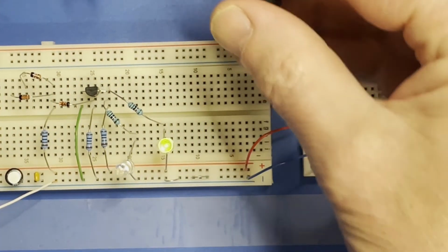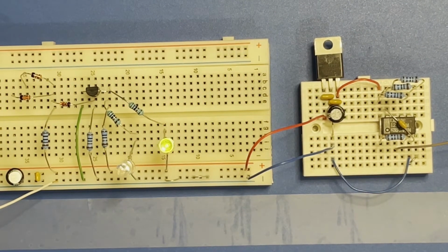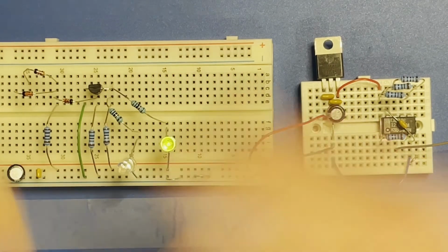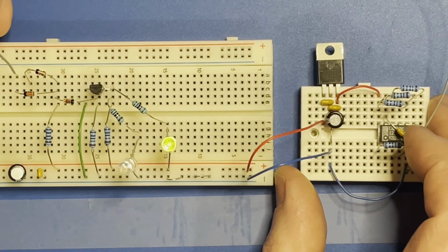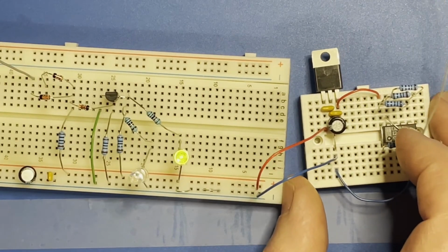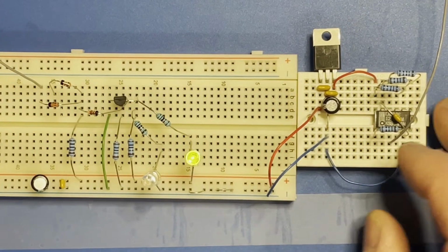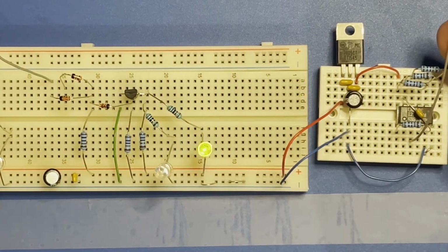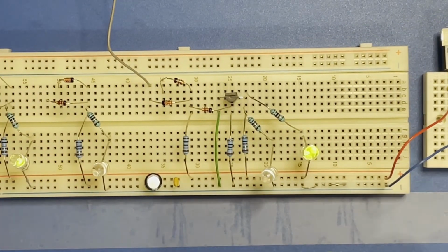So I'm going to connect that to the input of that gate. I'm going to connect the output of that to one of the inputs of this gate. I won't leave this in view; you don't need to see that. It's producing about a 1.5 megahertz wave from that signal, which I'll show on the scope. I just want to show what it was doing.